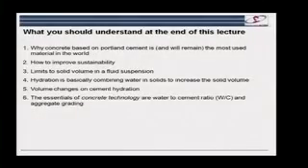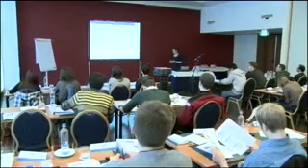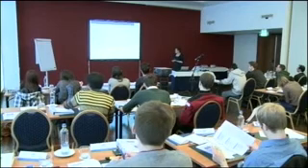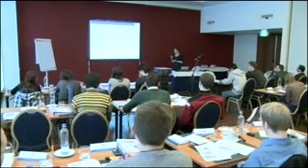So that's basically the end of this first part. What I really hope you've managed to appreciate is that it's all about volumes, that we're limited in the amount of solid we can put in at the beginning by the fact that it needs to be a fluid suspension, that what happens in this hydration reaction that we're going to go into in more detail is that we combine water with the solids to increase the solid volume, and that the two key things to do with concrete technology are really just about controlling the water-cement ratio and optimizing the aggregate grading.